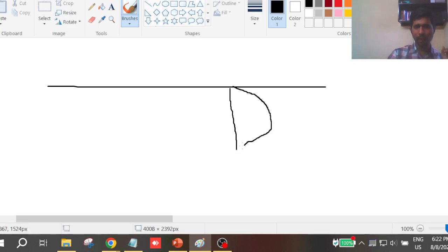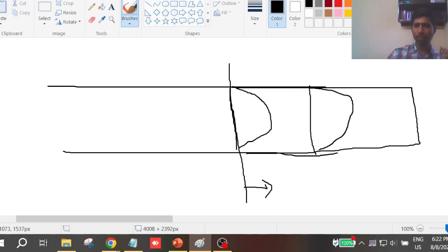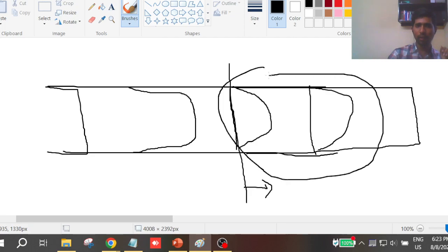What will happen after reaching a fully developed state is that the velocity profile will reach a parabolic profile. This is a simple channel problem. After this length, the flow field will remain constant. It's just that the pressure will drop linearly, that is not required. Before it, there will be a changing profile, and here it will be completely flat. But after this the flow will remain the same.